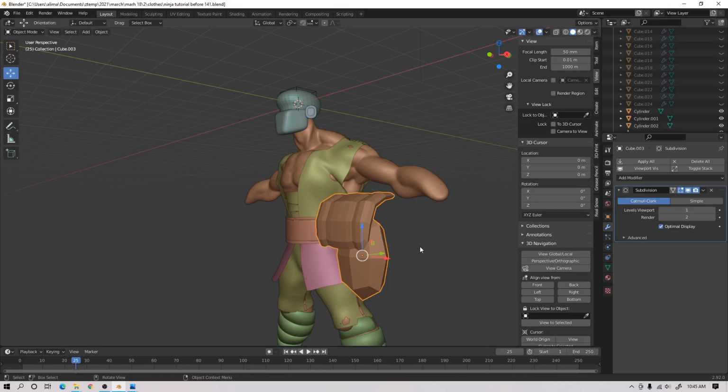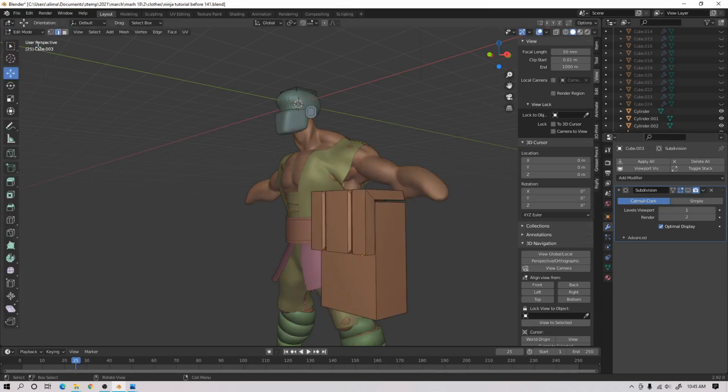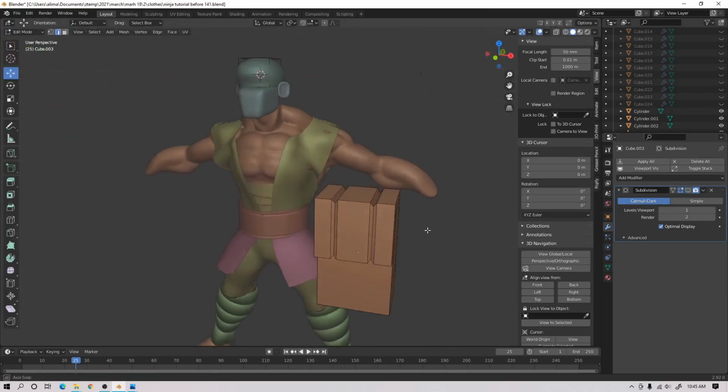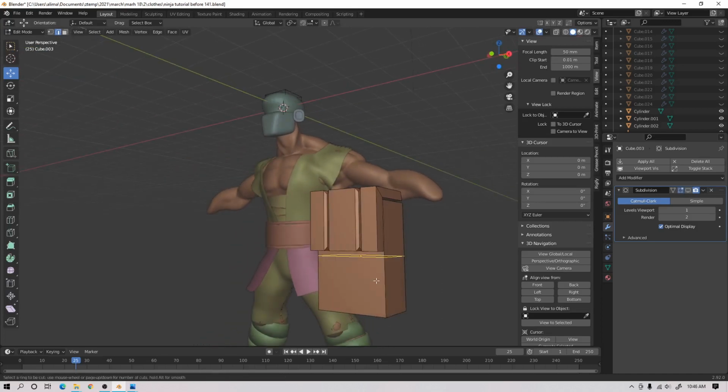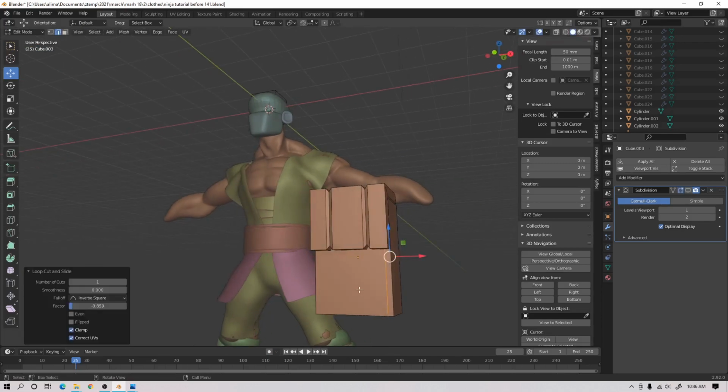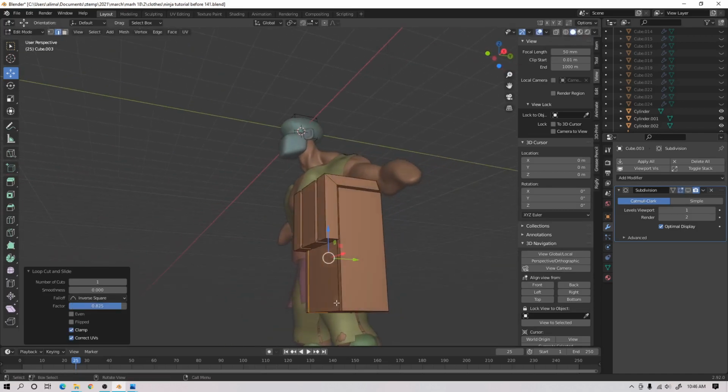Remember I told you about the loops. So we're going to select the monitor, right? We'll go in here. So what we'll do is we're going to put in a support loop. So we'll hold Control, press R, put in a loop. When you put edge loops next to an edge, things with a subdivision surface modifier on them tend to be sharp.